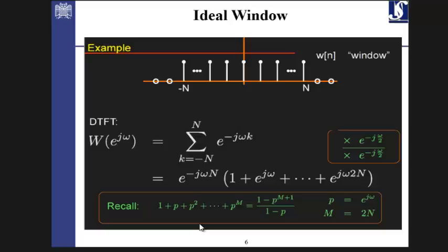So what you have to do is practically you have to put a window on part of the signal which is called framing or windowing, and then you will get the signal in that part. But when you go through the frequency domain, you should know the result of this kind of activity, what it actually brings up. The point is that windowing by itself somehow corrupts the signal.